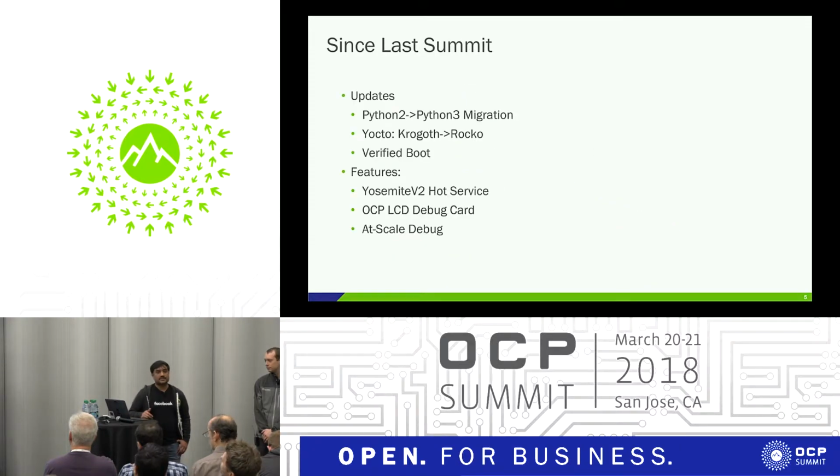So a couple of updates from the firmware component perspective, what features we added and what updates were done. One is the Python 2 to Python 3 migration. And with Yocto, a couple of platforms were able to move to Rocko. And on verified boot, we did a lot of work this year to make it production ready. Last year we showed there was proof of concept code, but this year we had to do a lot of work on the hardware front as well as the software front to make sure it works in all kinds of situations and to avoid bricked systems because of verified boot.